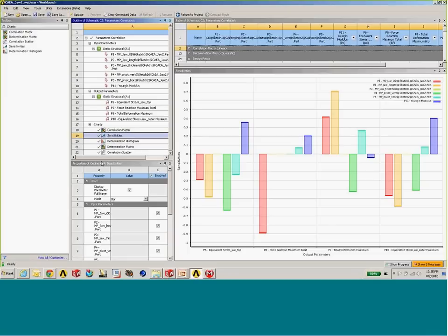To confirm that, we'll be looking at the global sensitivities of these parameters. If we go from output quantity to output quantity, displayed across the bottom here, we can see that there's virtually no response for parameter 3 for the various outputs. So that we're going to eliminate right off the bat. Looking at parameter 5, it has the weakest response of all the different parameters with the exception of 3. But the remaining ones, parameter 1, parameter 2, 4, and then P11, the Young's modulus, have a fairly strong coupled response with the output. So those are parameters that we're going to hang on to.